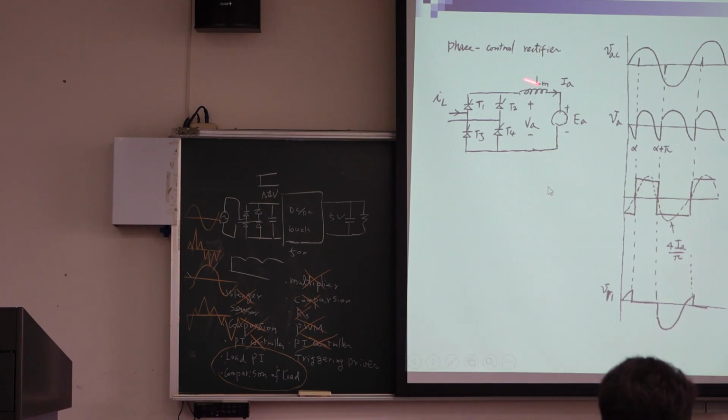So before, we use a DC motor, we control the DC motor. And then if we control the DC motor at a low speed, then the power factor becomes poorer. If we control the DC motor for high speed, then the delay angle is small, then the power factor is higher.